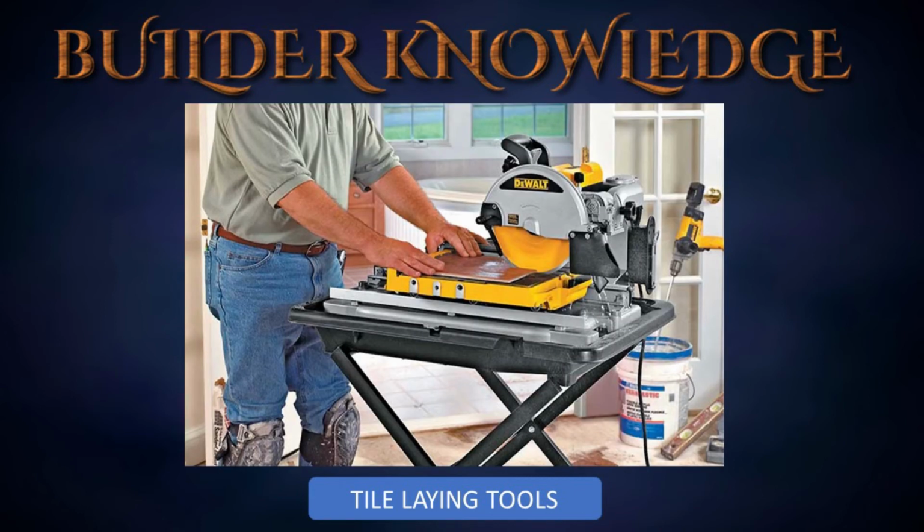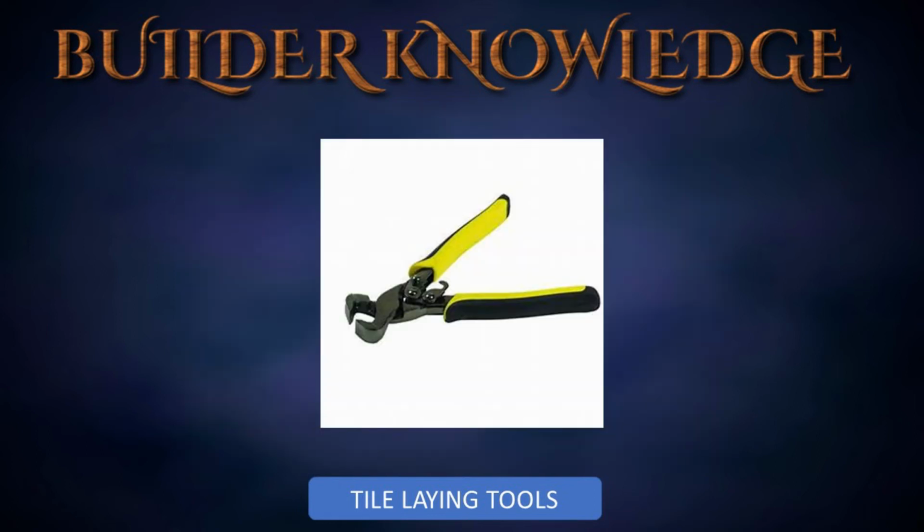The tile saw or wet saw is used to cut tile and stone. It uses a diamond-tipped circular blade, cooled by a continuous stream of water, contained in a reservoir. It operates like either a radial arm saw or a table saw. Tile nippers are used for trimming irregular shapes. When using the tile nippers, it is important to nip off very small pieces of the tile. Attempting to take big chunks at one time can crack the tile.